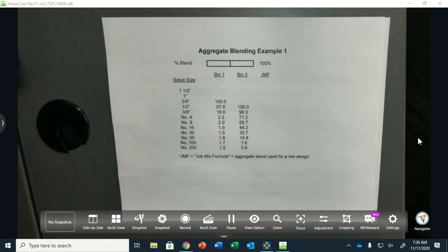That's very critical in asphalt, because remember that asphalt layer on that road is only this thick, so those wheels are beating on that, right? So those can break, okay? We need fractured faces. We actually want 2 fractured faces to create that friction, okay? And then all the same aggregate properties like toughness, freeze-thaw resistance, LA abrasion, P200, those are also important in asphalt, okay?